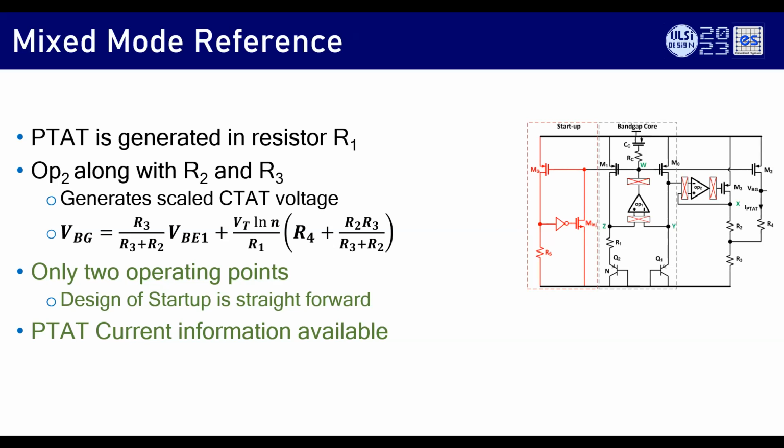So this we developed in our lab. There's a voltage mode, there's a current mode, and we call this a mixed mode reference, because what we did was, look, in sub 1 volt we cannot design a bandgap because the CTAT voltage is more than 800 milli at minus 40. So why not divide the CTAT voltage and then add a PTAT. That is precisely what we did.